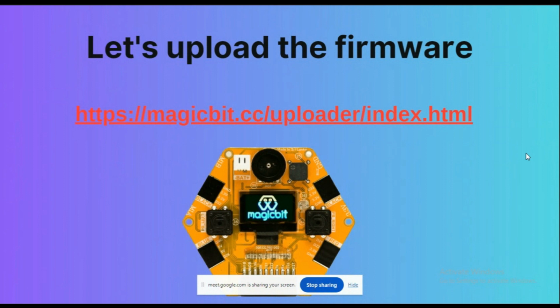If your Magicbit doesn't have the MicroPython firmware, you can log into the Magicbit web uploader. The link to the uploader is in the description box below. You can click on that and get into the uploader. There you have to connect the Magicbit with the uploader and install the MicroPython firmware. After installing the MicroPython firmware, you can disconnect the Magicbit from the uploader, unplug the Magicbit and replug it in order to restart your Magicbit with the MicroPython firmware.